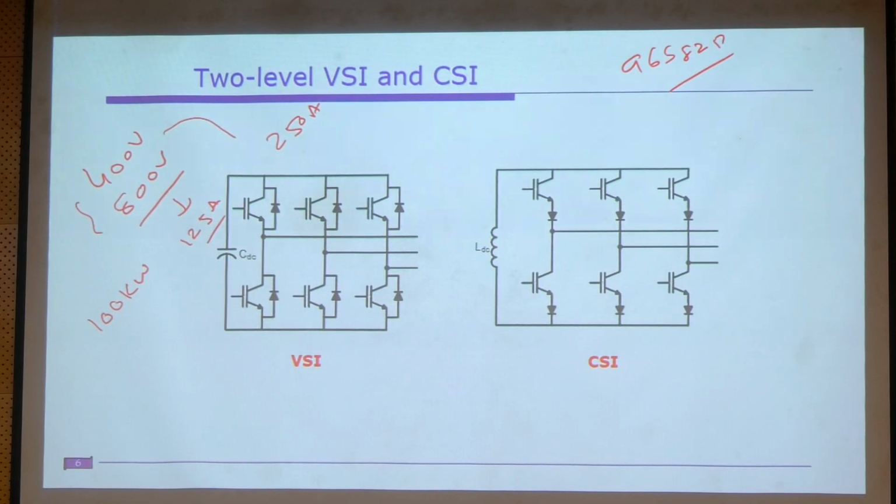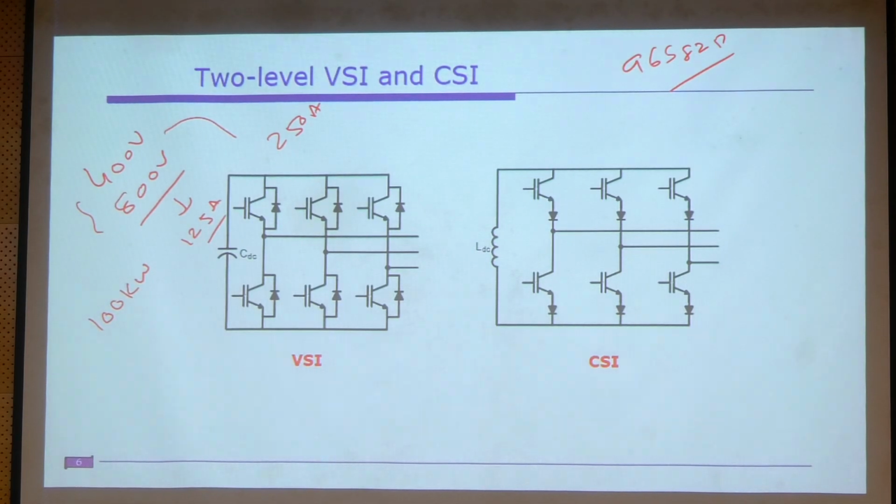Another advantage is the charging speed. If it is 800 volts, we can inject more current. Nowadays 350 kilowatt chargers are also available. By using a 350 kilowatt charger, a 60 kilowatt hour battery pack will maybe charge in 15 to 20 minutes, roughly, right? So charging time can be drastically reduced, right? Understood?